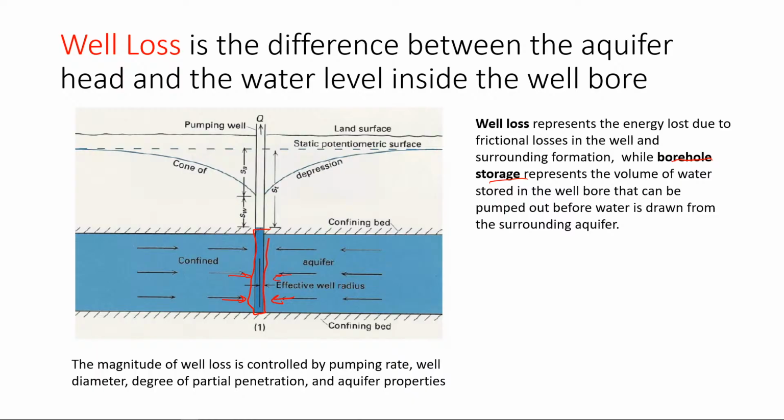And usually pumping tests are generally not conducted after you develop your borehole. It's usually conducted after you drill. So you drill your borehole, and before developing your well, you start your pumping test. And in that case, you can minimize the impacts of borehole storage. But if there is borehole storage, then you need to take this into consideration before you get meaningful data for your drawdown time curve.